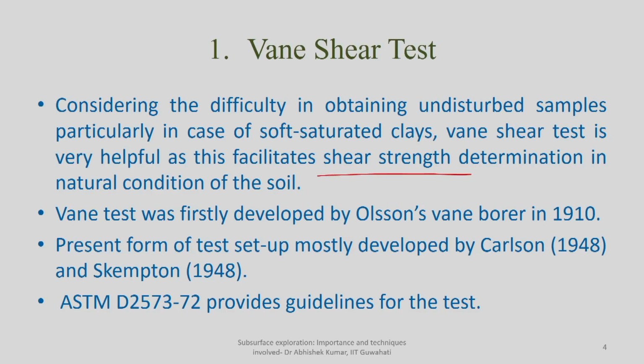You need not bring the soil sample up; if the soil is available at 8 meter, 10 meter depth below the ground surface, you need not bring it to the surface and take it to the laboratory to determine the shear strength property. You can determine the shear strength property there itself, in the natural condition of the soil. Because you are not bringing it up, the soil is not getting disturbed or altered, and you are assessing strength at the natural ground conditions, whatever the depth of investigation.